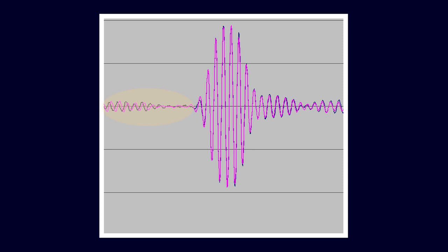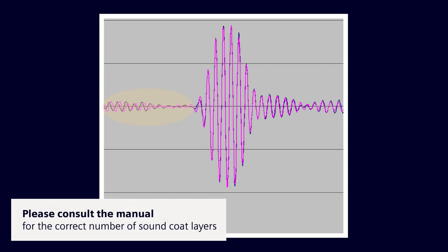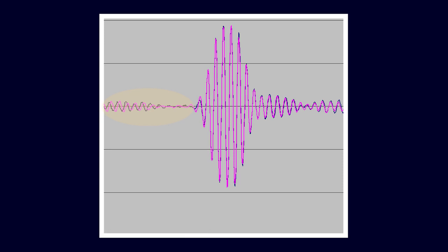This can either be caused by not applying the correct number of layers of dampening material, or CC129, or we could have a relatively poor wall thickness to pipe OD ratio, in which case if you're on reflect 2 traverse, switching to reflect 4 traverse may alleviate this. Or if you were mounted in direct 1 traverse, consider switching to direct 3 traverse.